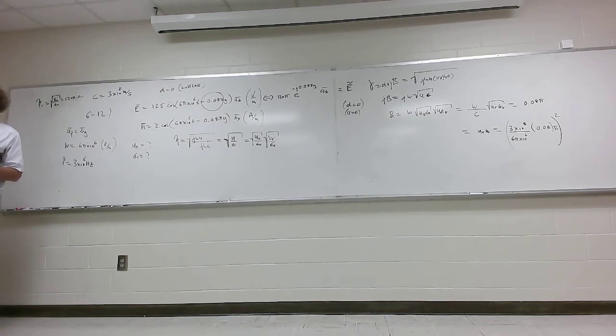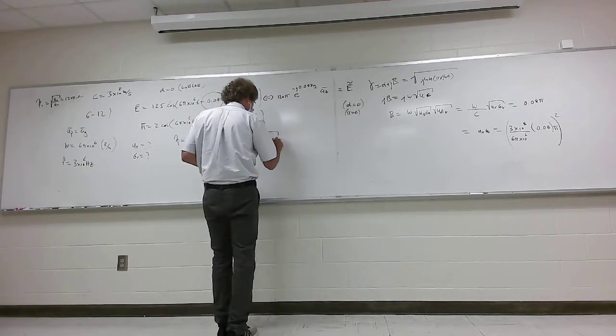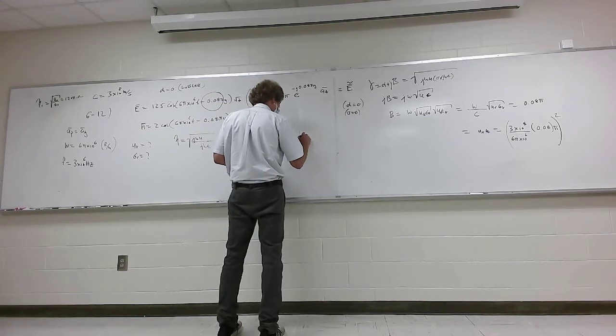These are things that are, it's like teaching circuits and assuming everybody understands V equals IR. If they don't know that, everything else is a wash. You can't do it. And it's the same way here with these basic concepts. You have to know them all. Now, I'm going to go down here and just say, well, this is equal to 120 pi times square root of mu relative epsilon relative.